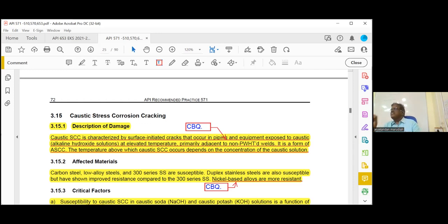If we keep a permanent sensor or probe to pick up the sound, we can monitor the growth. So that is called acoustic emission testing. In a storage tank, acoustic emission testing is used because even if the tank becomes brittle during service, it will not fail brittly. When will it fail? I told you, during hydro test.